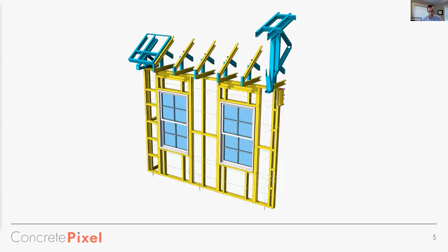And another seemingly small but significant item for coordination, especially at this stage, is actually pretty easily handled in BIM. And that's trusses bearing directly on top of vertical wall studs. That really helps improve the structural quality and performance of light gauge steel. Structural details being modeled in parallel with documentation not only helps ensure a more completely engineered structure, but also tees up the next stages of development.